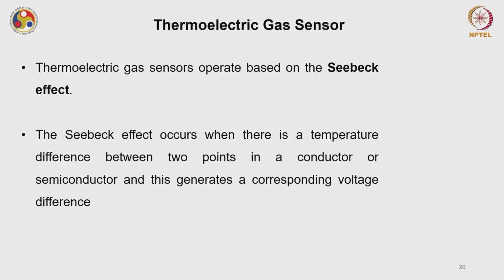Then we have seen that there is another kind of catalytic sensor which is based on the thermoelectric principle, or we call it a thermoelectric gas sensor. A thermoelectric gas sensor, as any other thermoelectric device, works on the Seebeck effect. The Seebeck effect occurs when there is a temperature difference between two points in a conductor or semiconductor, and this generates a corresponding voltage difference.